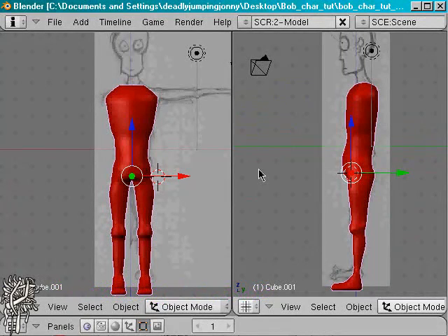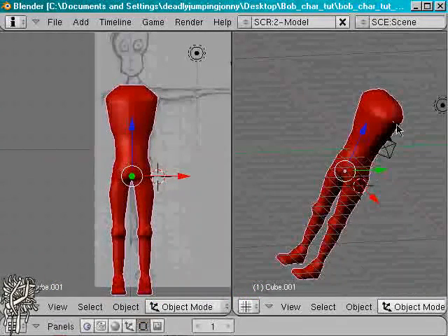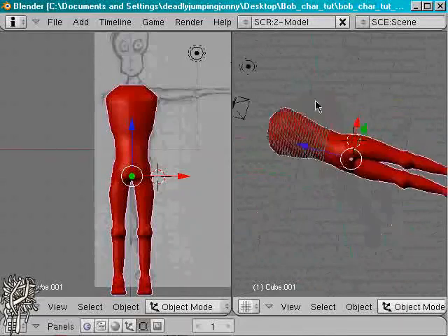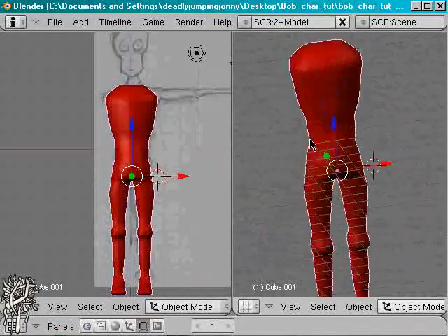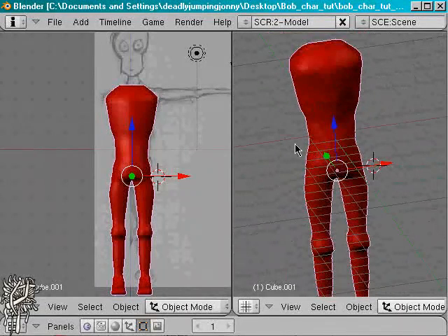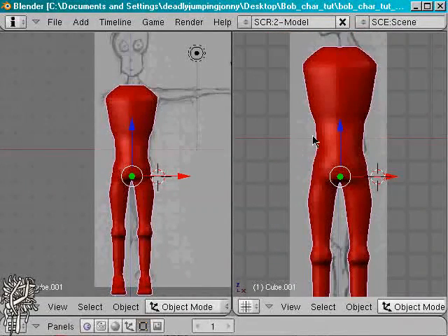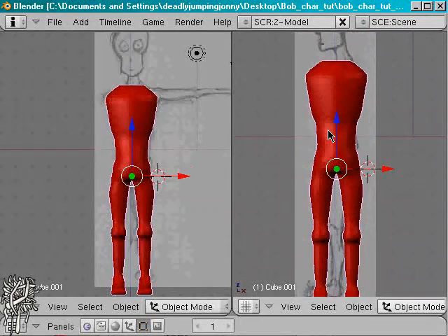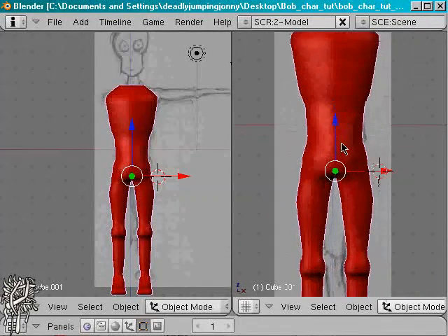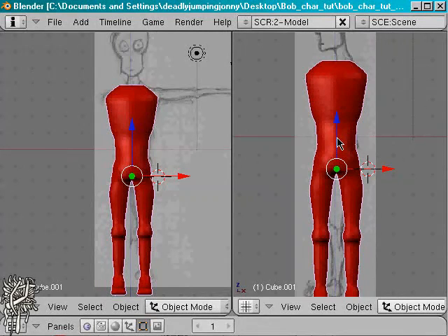We're doing this because we want to extrude our arm without the hassle of doing all the extra work of selecting one side, going to the other, selecting the same vertices or faces. It's just a lot quicker this way, and since our model is symmetrical, we can just duplicate and mirror it straight after we finished. Or we'll be doing something a little different though. We'll be creating a mesh with the same data, so both sides will be modelled at the same time. But we'll go into that in a second. First off, we're just going to cut the mesh up.